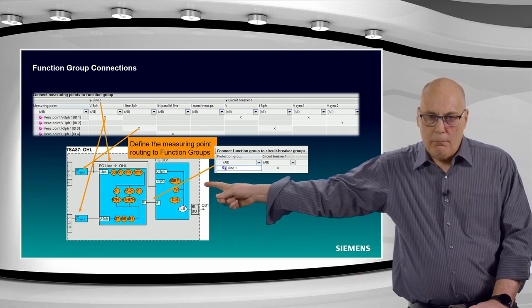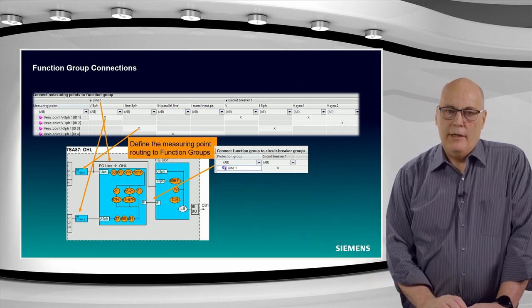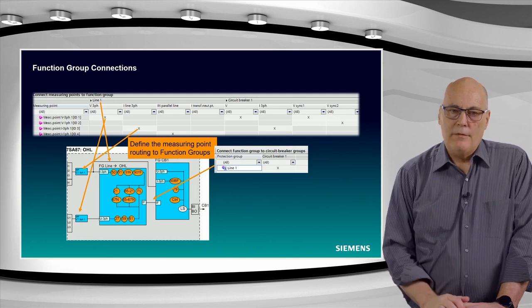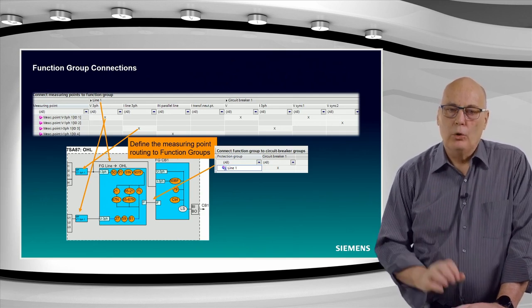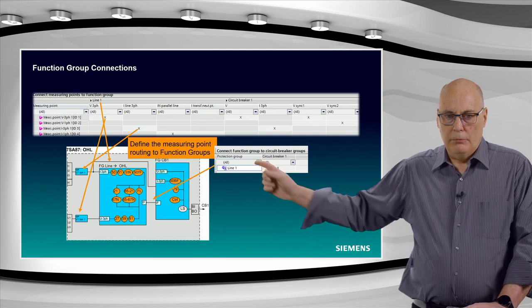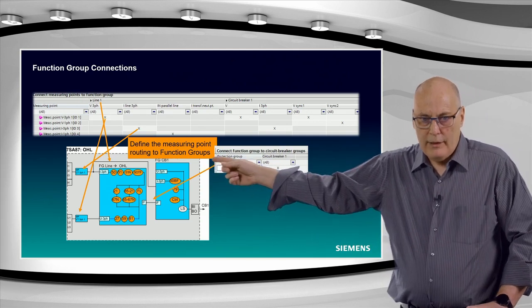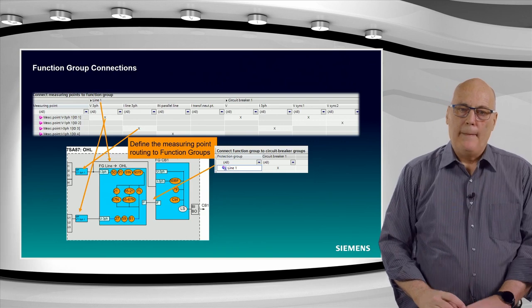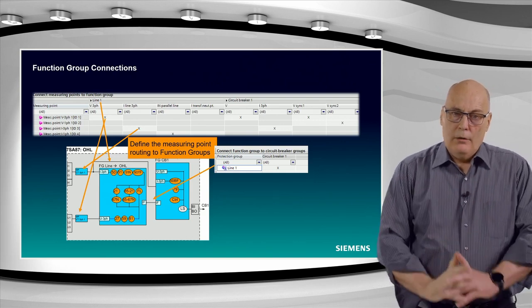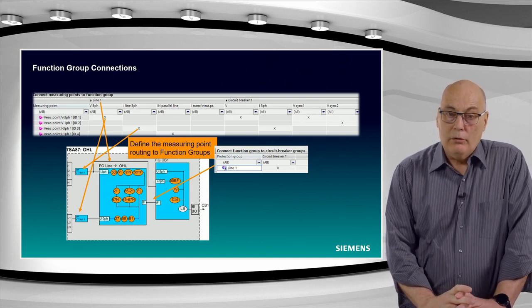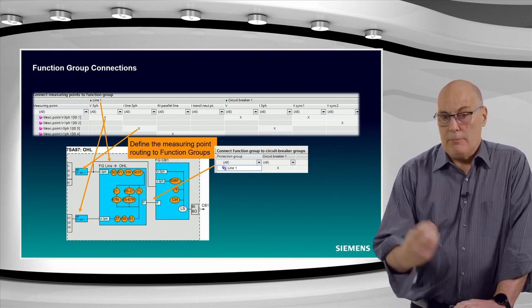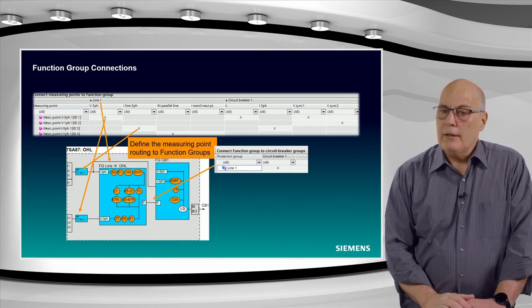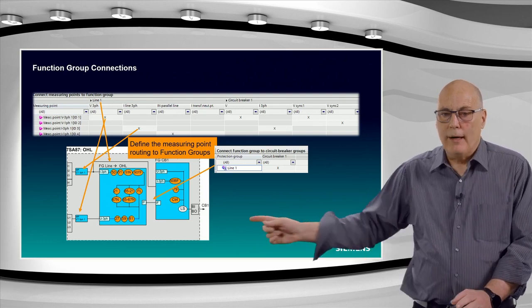And you see that middle blue block there. In the middle there's the 21, our distance protection, and it derives its measuring point from this function group line. And as I say, the logical measuring point current, completely on the left there, is used in both function groups, the function group circuit breaker and function group line. The trip command that we route out, and also the feedback, the status, because there are functions in the line that need to know the status of the circuit breaker, that you don't derive that directly from the outside.